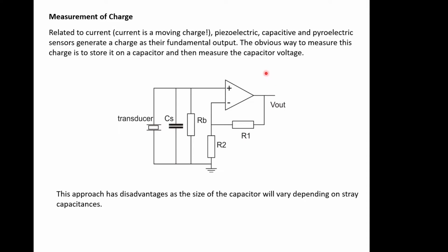And that's what we tried with the current source, and we noticed that that actually introduced a few little issues in terms of this capacitance not being in the virtual ground. We've had to introduce RB here to allow some bias currents in, because as drawn there's no way that we can get DC bias currents into this positive terminal, because the transducer only provides charge, doesn't provide current.